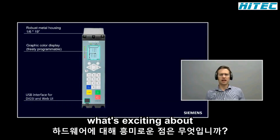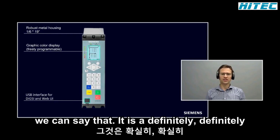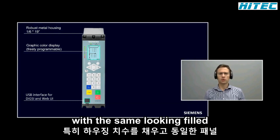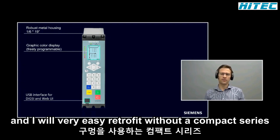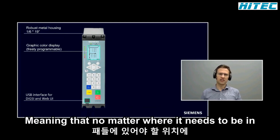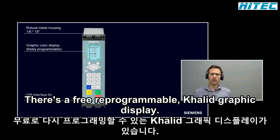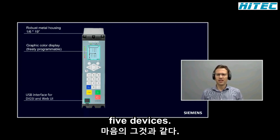So, what's exciting about the hardware? Well, clearly, when we look at the SIPROTEC 5 Compact, we can see that it is definitely a part of the SIPROTEC 5 family with the same look and feel. The housing dimensions in particular enable very easy retrofit with our older compact series devices. It uses the same panel cutouts and mounting holes, meaning that no metalwork needs to be done in the panel for a retrofit application. There is a freely programmable coloured graphic display. The resolution is identical to that within the main SIPROTEC 5 devices.